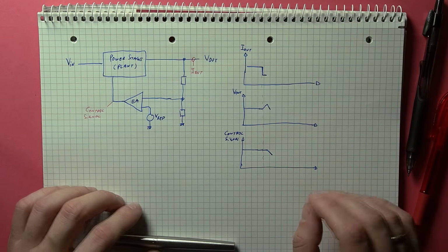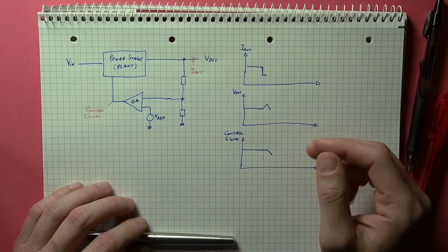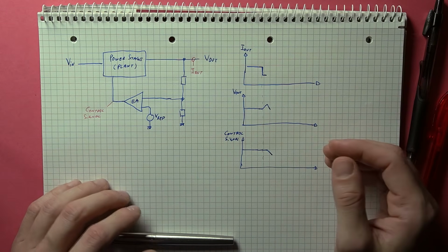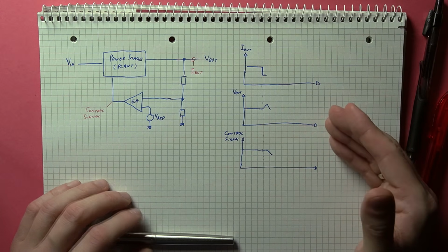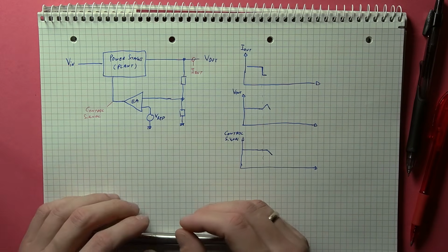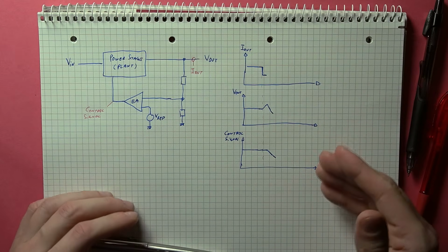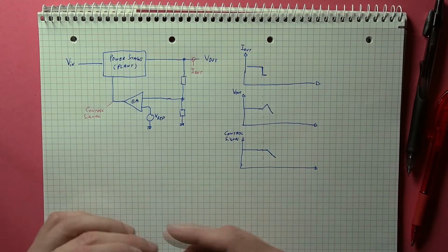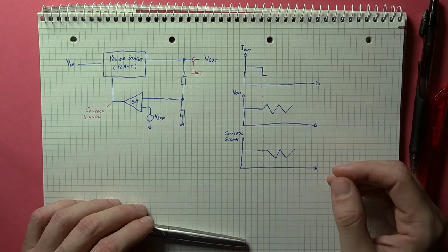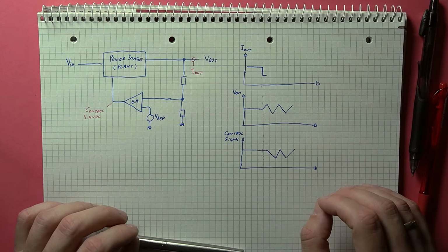Now, the next thing to observe is the magnitude of the change. Ideally, you want the output voltage to perfectly stabilize to the previous value. However, if the reaction to the perturbation is too strong, and it's coupled with large time delays in the system, the output will end up dropping too much, which will lead to the error amplifier again giving the order to increase the output voltage again. And this can lead to an oscillatory output, something that you definitely don't want.